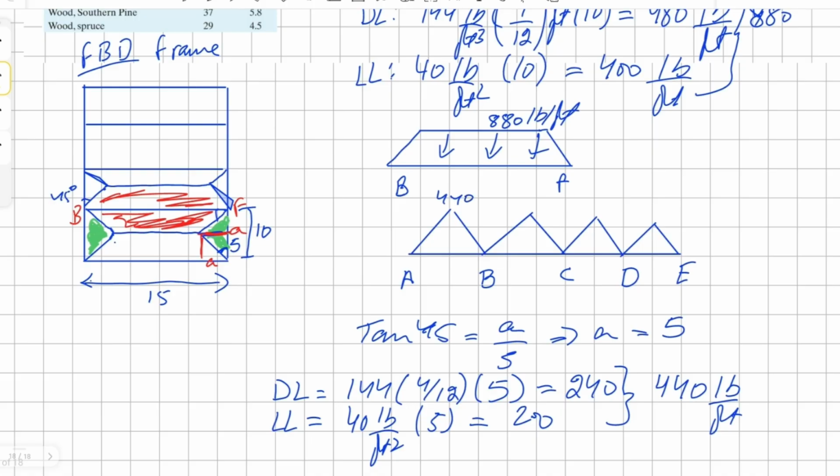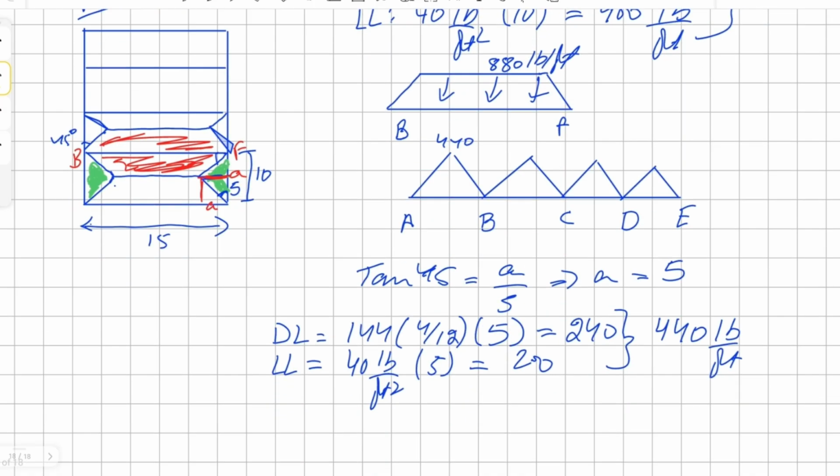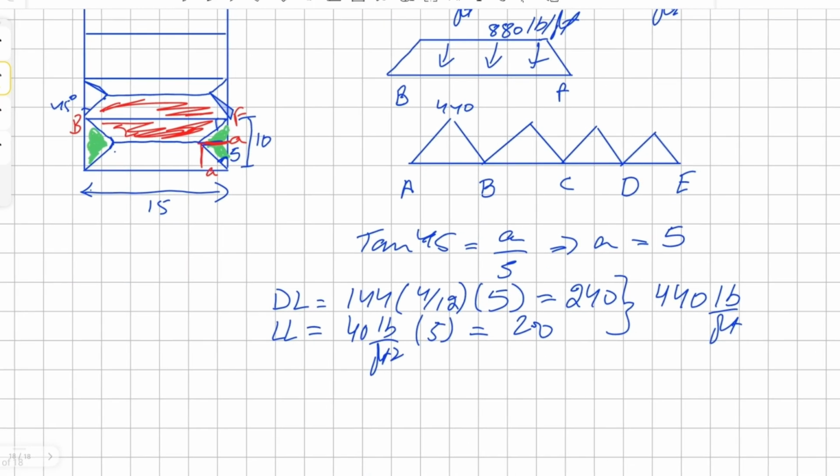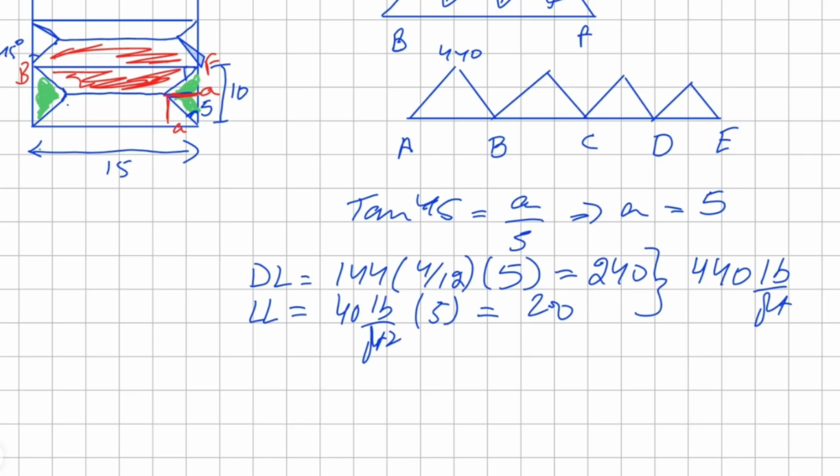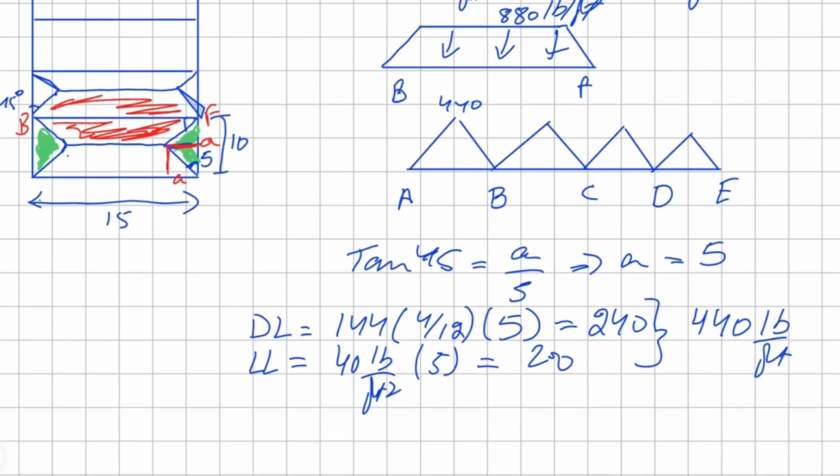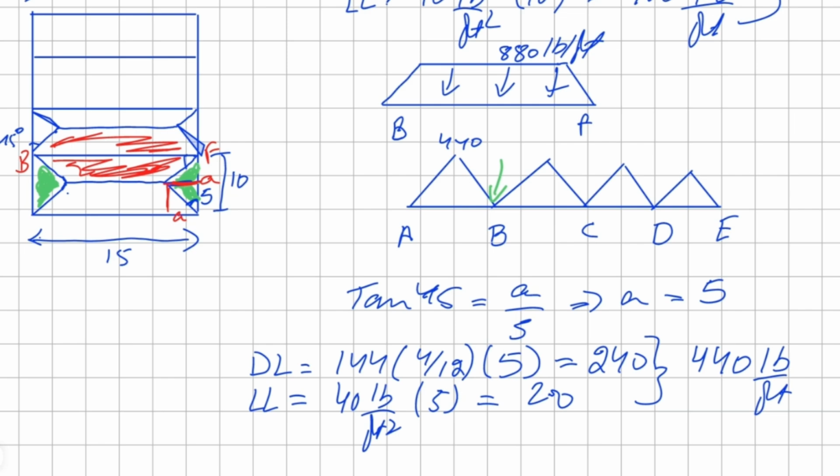And the easier way to solve the same value is simply dividing our peak load for our joist BF, and we'll get the same value. But I just wanted to show this in the problem as well. Let's find the point load for B. First of all, let's transfer our point load from joist BF, and we know that whatever our point load for B is, it's also going to be the same for points C and D.